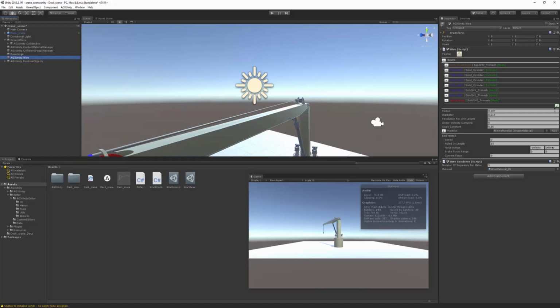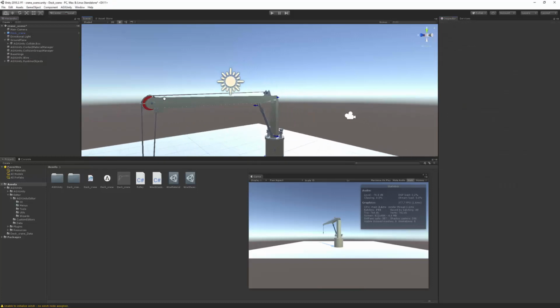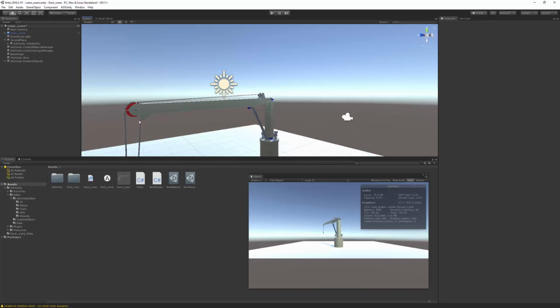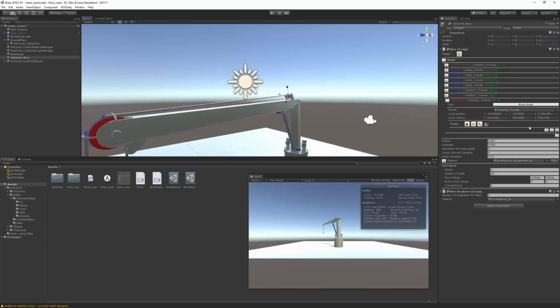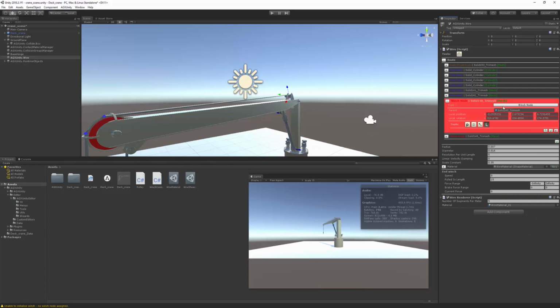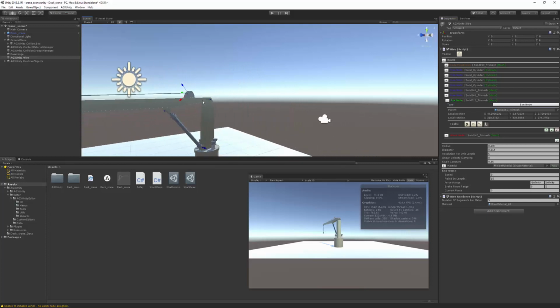So just for demonstration, I will show you that we can also create what we call an I node. An I node is a specific node which the wire has to go through, and the I node can be attached to a rigid body. So if we create another node just before the winch, because the winch is the last one, we just select the wire and we select the winch node, and then we say create a node before, and we select it to be an I node, and we specify that the parent is this crane boom.